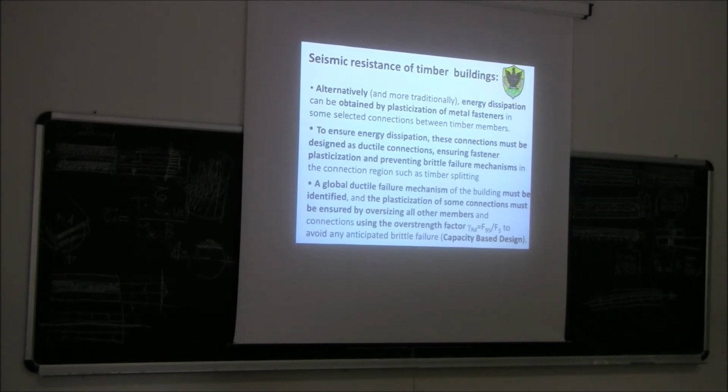So, first of all, you design the beam for what? For bending moment or for shear? For bending moment. And when you design the beam for bending moment, particularly in these critical zones, you took into consideration the value of the bending moment coming from the analysis. So the one coming from the reduced elastic forces. And in this way you did the design for bending. Okay? Then, when it came to shear, what did you do that time? Did you take the envelope of the shear forces, like you've done for the bending?